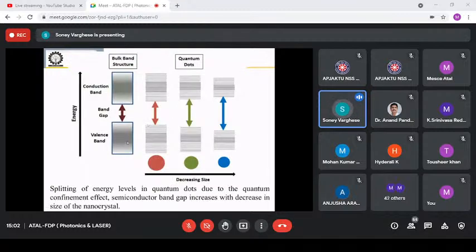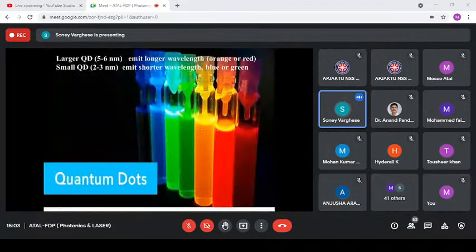As I told you, in quantum dots, as the size goes down, the band gap increases. Similarly, when you use it for display applications, you can tune the colors, because in most cases we are actually not changing the LCD as such. On the color filter, as I told you, we have red, green, and blue. In the color filter, people are starting to use quantum dots, right? So you can see that these are wonderful colors you can expect from quantum dots.